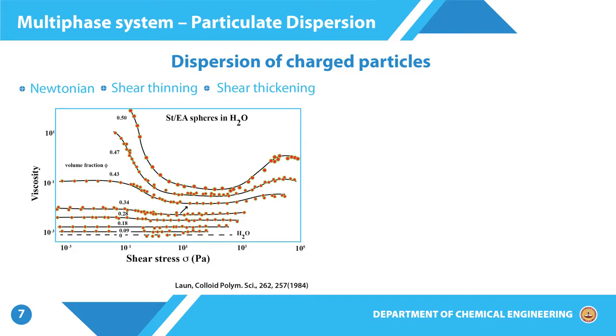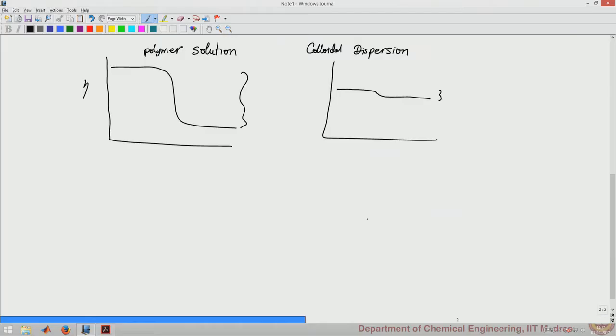Now, we are talking about 4 orders of magnitude increase over the solvent viscosity, and such an increase is only possible if we have percolated clusters, and this is what we saw in terms of colloidal glasses or colloidal gels. If you have such percolated clusters, then solvent can remain trapped in these, and therefore a significant amount of stiffness and other properties can be expected. So, we have a percolated cluster which corresponds to very stiff properties, or in this case very high viscosity.